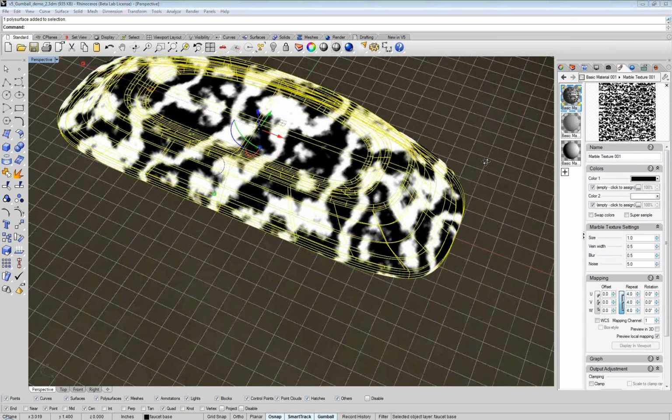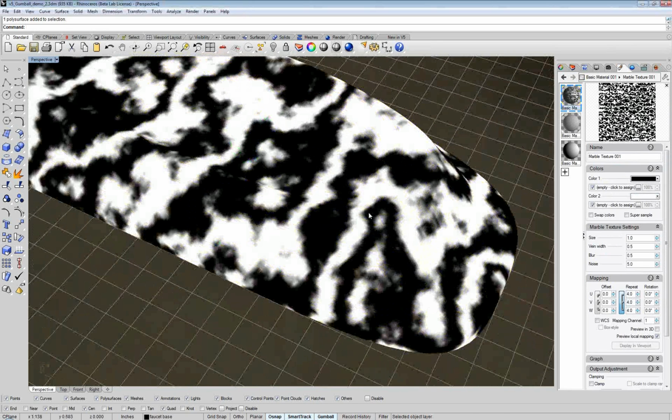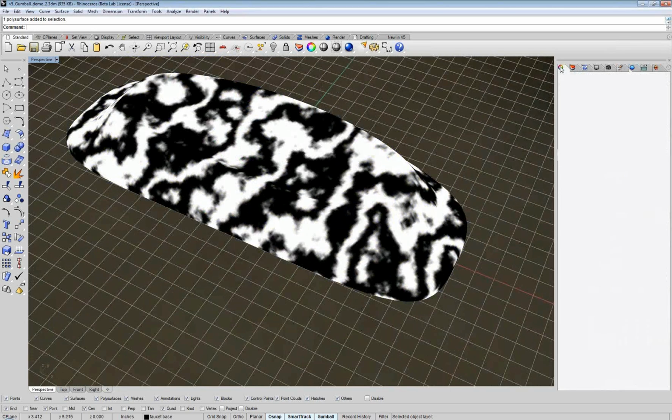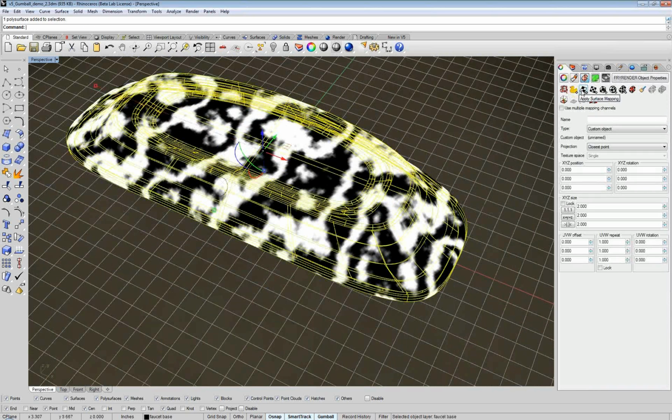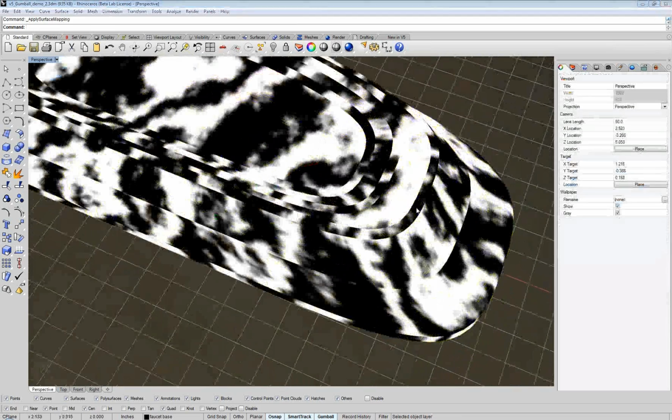Now if you had a regular surface mapping method, which is the default, you would see it break. This texture would break as it passes between the seams and the polysurface. So let me go back to the texture mapping, and I'll change it to surface mapping just so you can see that. So that's the problem with mapping with just primitives, is that if we used a plane or a box or a sphere, we wouldn't actually get a continuous display of that texture across that seam.